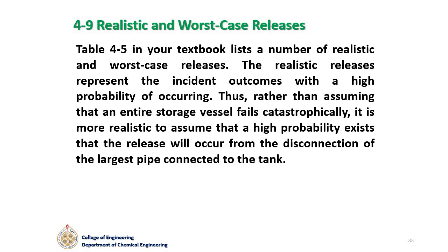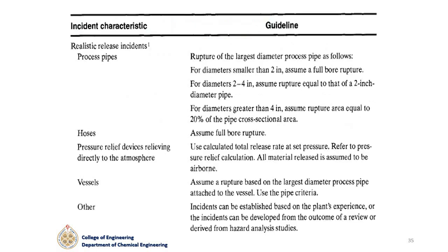The final thing I want to mention in this chapter is the worst case scenarios, where we assume an entire storage vessel, for example, fails catastrophically. For example, you could have a rupture of the largest diameter process pipe, as follows. For diameter smaller than 2 inch, assume a full bore rupture.